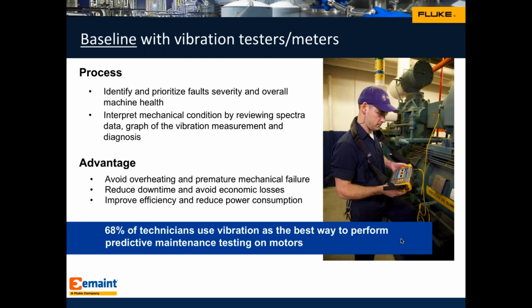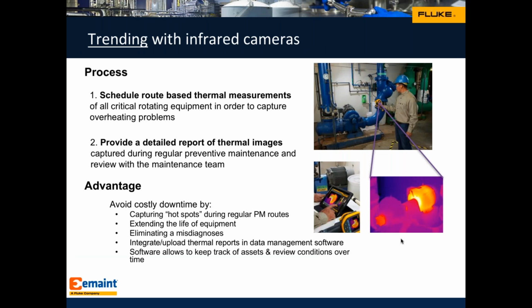And so those are the quick things from a screening and baselining standpoint that you can do on vibration that can really help start getting confidence in the technology, and will also make an impact for my preventive program. So obviously, along with the baseline is the trending, and the trending is to try to establish a scheduled route for either thermal imaging or vibration, as you'll see on the next one.